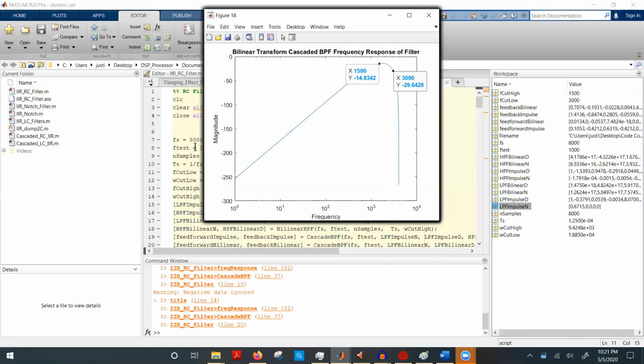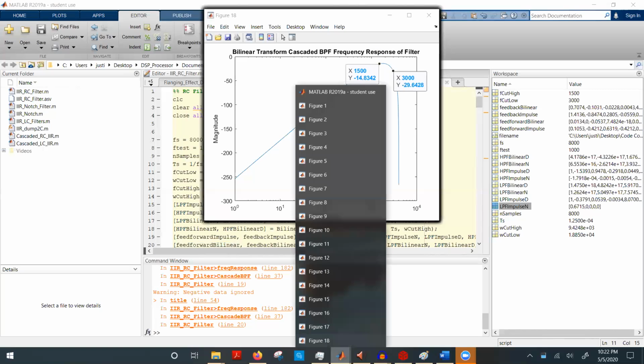And that's because we're approaching the limit. If I set my sampling frequency to 8000, we're approaching the Nyquist frequency of 4000, so we've lost the linearity. So this doesn't exactly match the actual filter. But that's okay, because we can still run this filter. It just won't operate exactly as the actual filter. This is for the bilinear, because the bilinear has this nonlinearity when you approach the Nyquist frequency.